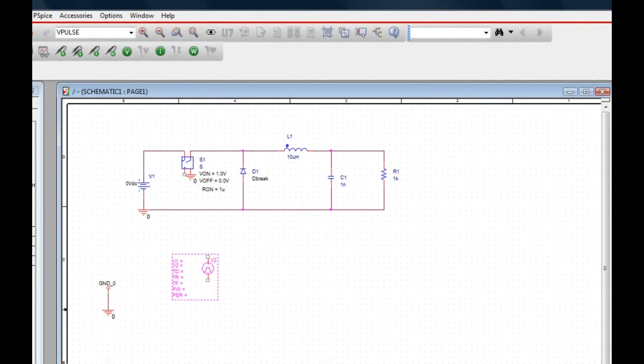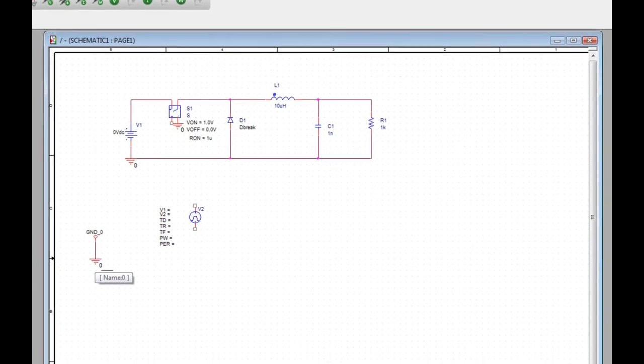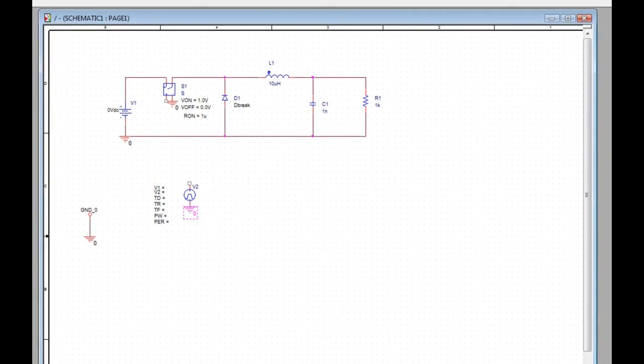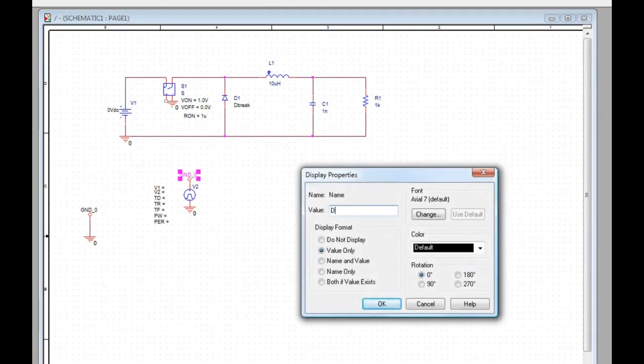And it's basically a gate pulse of various widths that we can apply to this threshold input, this control input, to turn this main switch on and off, which is effectively what the MOSFET does for us. And I'll put a ground over here, Control V, cutting and pasting it. And let's make something a little cleaner, and let's put this ground symbol up here, but of course we'll change the name of it to gate.